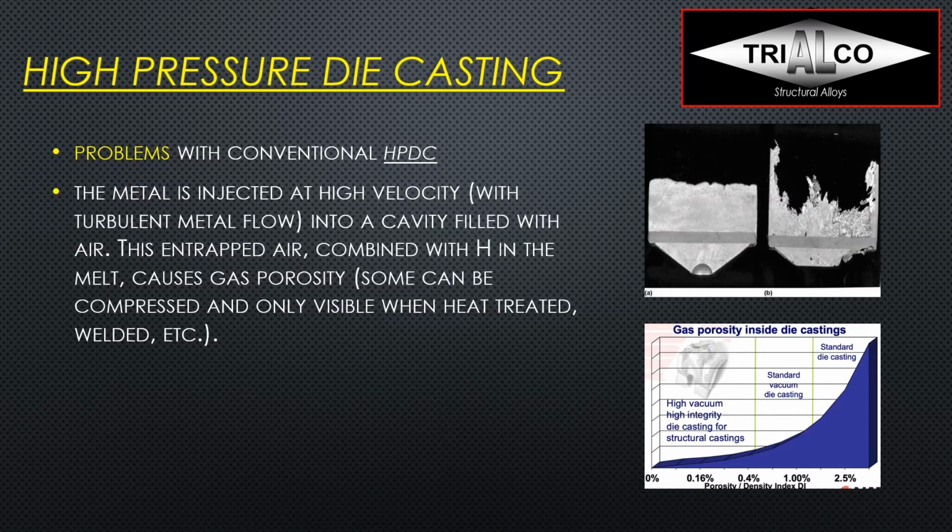So the casting might be fine, and that's why it is used for a lot of applications, because if you don't heat it to high temperatures, you won't see anything. And you still have the skin effect, so you'll have good fatigue properties. But it might not be suitable for impact, for example, and if you heat it up too much, you will see blistering because the gas porosity then expands, and the hotter the metal gets, the softer it is. It also cannot be welded, and certainly not brazed, and a lot of problems that you get when you have porosity appear. You also get shrinkage porosity, despite the high pressure to intensify it.